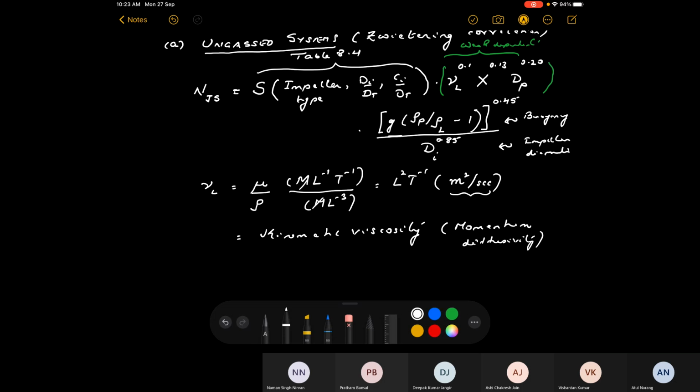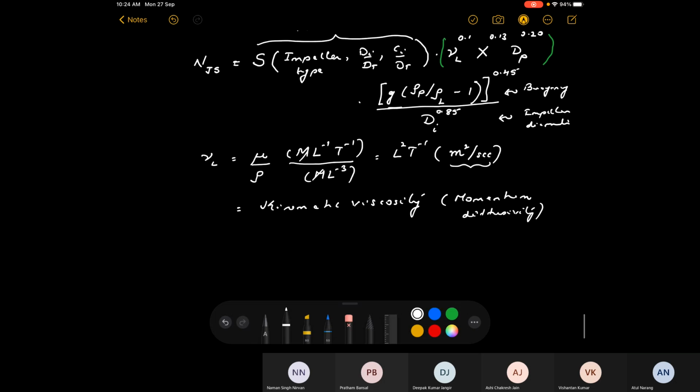So it's really the real measure of the intrinsic tendency of momentum to be transferred by diffusion as opposed to convection. Okay, so it's not viscosity alone; it is viscosity divided by rho that really tells you what is the diffusivity of momentum transfer.